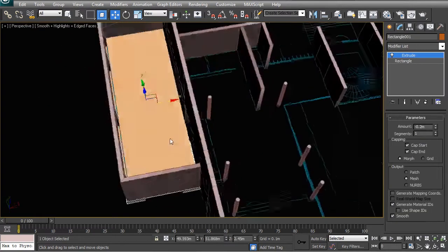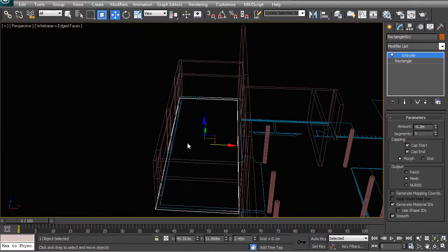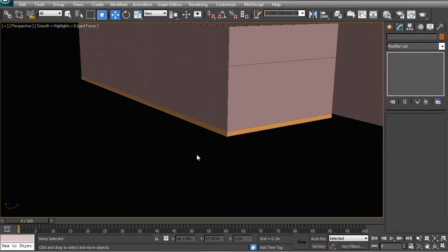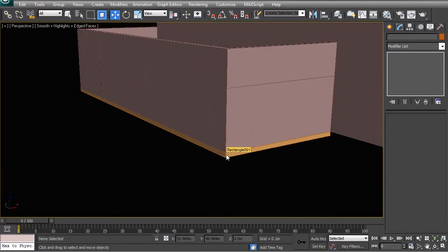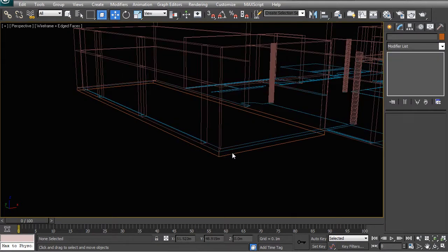It works fine when you're working on interiors because you get this nice and cleanly done, very simple object. But once you start working with exteriors, especially if you start applying different floor textures to your floor slab as you would to your walls, which you very often do, you then start to see these edges. And this is especially important when you do multi-high-rise buildings. You don't want to see those edges of the floor slabs on the outside of your walls. So this is definitely something that you should not do.